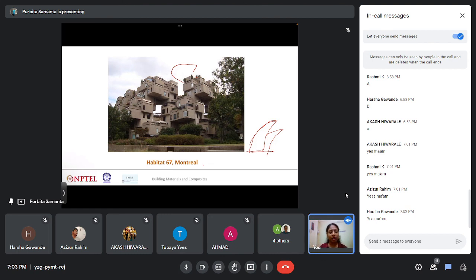Also when it comes to modular construction, there are several other things which you can check, for example the structural grid of modular construction. There are different types of grids. It can be a rectangular grid, a square grid, or a tartan grid. When it comes to modular construction, generally you follow a particular grid. So here you place your first unit, then this unit, this unit, this unit. So this is one grid. Then this can be another grid, right? Then this can be another grid. I'll show you. So this is basically what a tartan grid is all about.